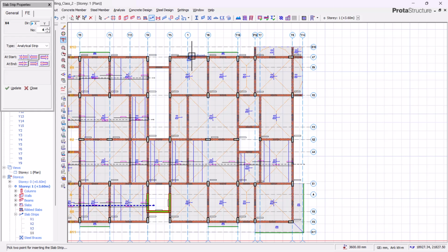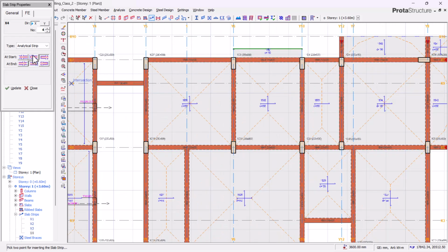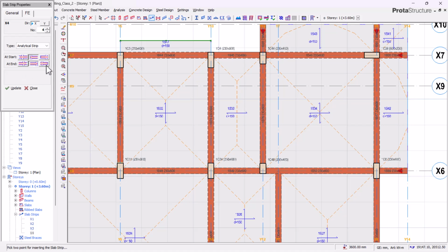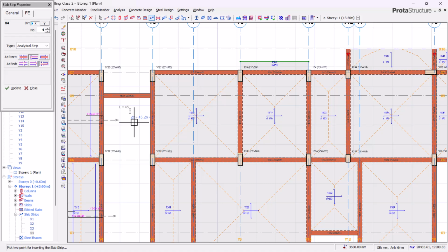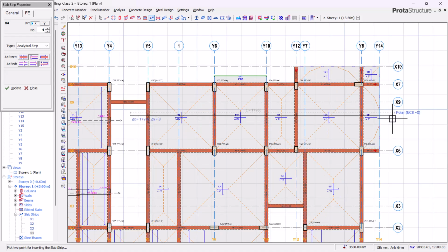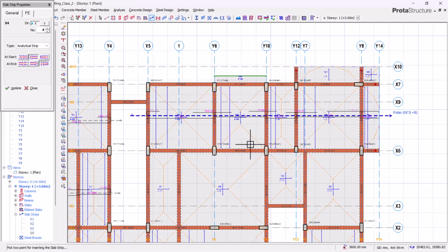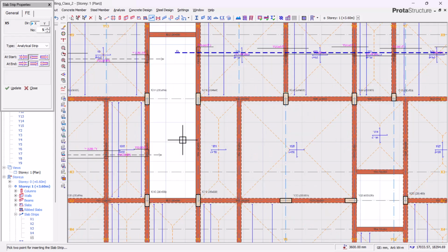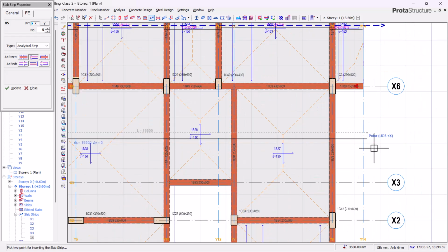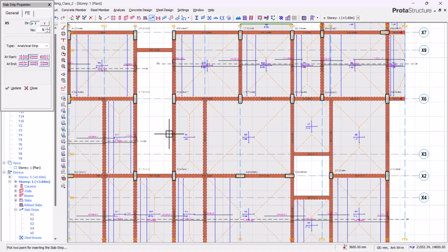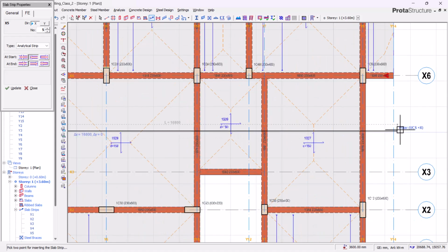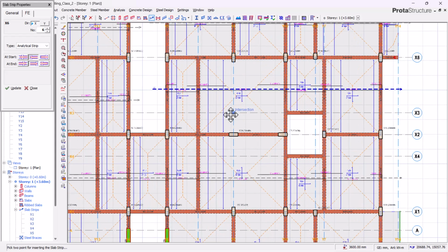And this other panel over here, we are still on the x-axis. We come to this other part. At the start, we'll be going with bob and ending with a cantilevered slab. So bob and cantilever. We'll click here, and we'll click here. The next is bob to bob. So we'll click. We are designing from our story one. In case we have any failing slabs, we can remedy that and apply it to subsequent stories.